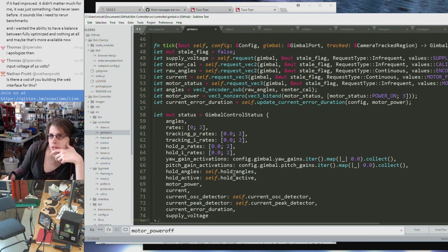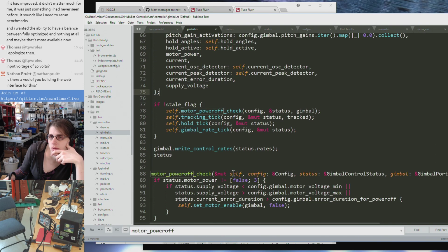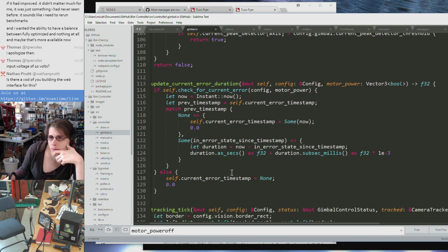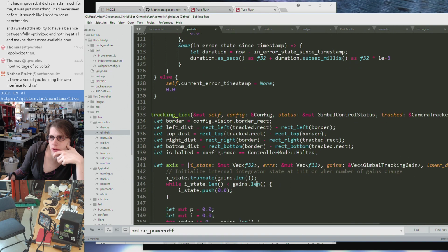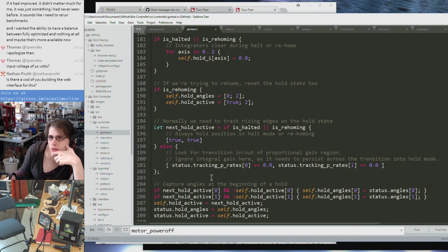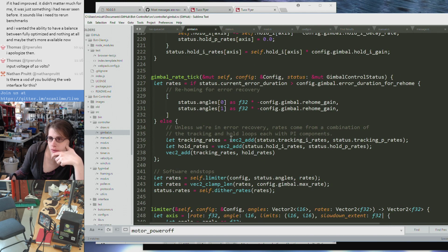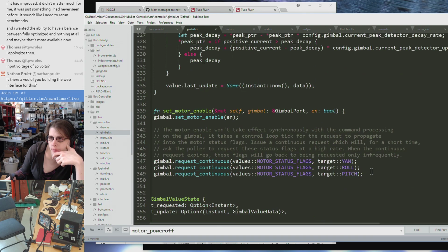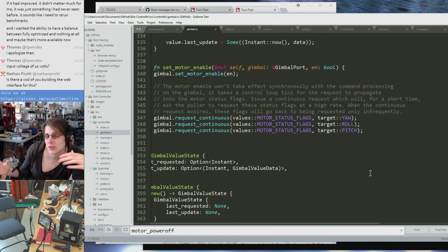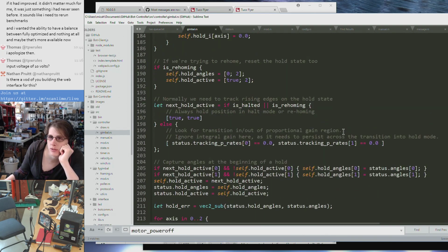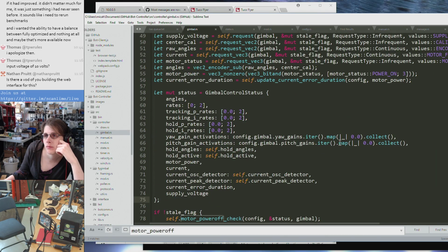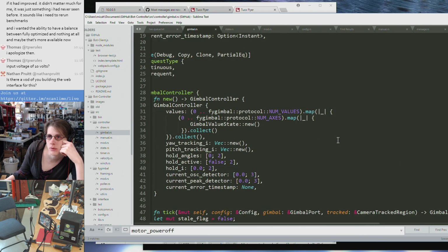So when would we want to actually send parameters to the gimbal? I mean, we could just register an infrequent poll operation for all the parameters, such that every n seconds, you look at that parameter, and if it's not the value you expect, then you send it. But you can imagine if they bunched up all at once, then that could be kind of bad. You start to have to think about scheduling those if you have that giant block of commands all being issued at the same time.